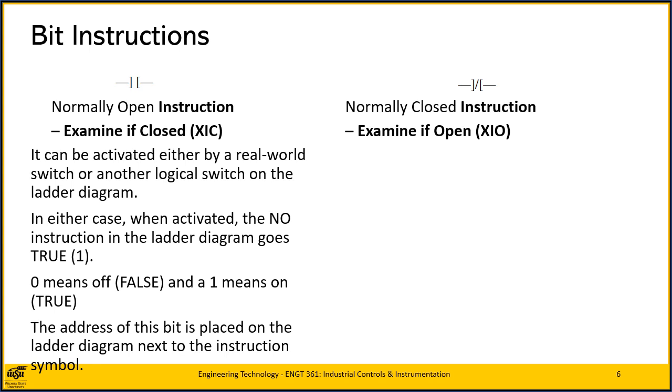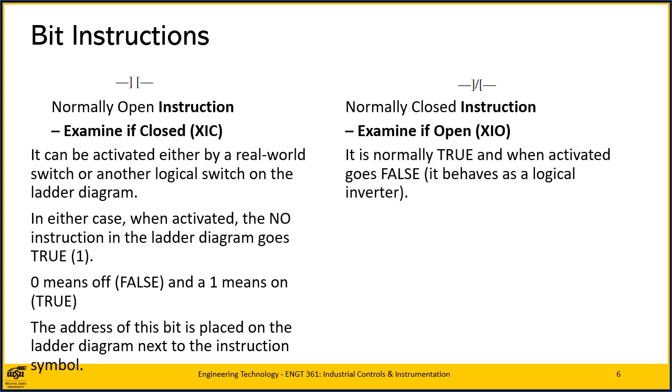When this symbol is placed in the ladder diagram, it behaves logically in the same way a normally closed switch does. That is, it is normally true and when activated goes false. It behaves like a logical inverter.